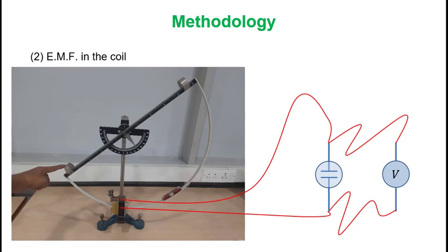And then the value of nE will be measured by the voltmeter, which when divided by n will give you the EMF. Yet there is another issue. While oscillating the magnet, the EMF of both signs, positive and negative, will be generated in the coil that will reach the capacitor and will cancel each other during the charging of the capacitor. So ultimately, the capacitor will not get charged. To overcome this difficulty, let us connect a diode with any terminal of the coil. This diode blocks one direction of the current and the capacitor gets charged to nE voltage by n oscillations of the magnet through the coil.